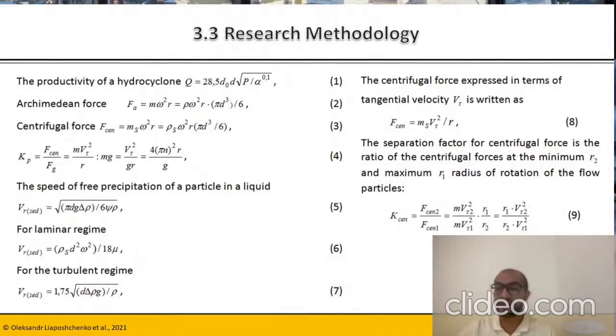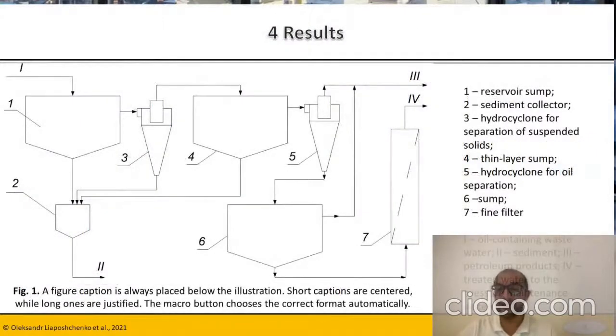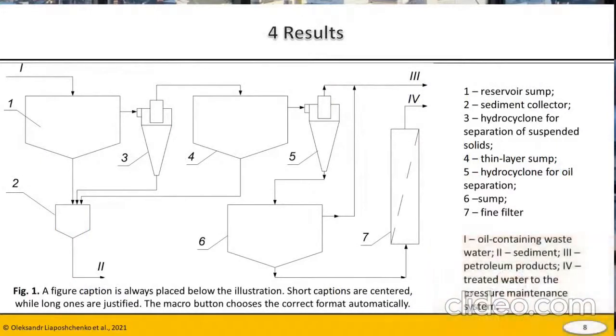The device implements a mechanism for separating light oil and gas from the heavier fraction, water. Next slide. In this slide, multi-hydrocyclones make it possible to achieve a deep degree of purification, and their use is promising both in the oil-containing wastewater treatment system and in the system of primary water discharge.